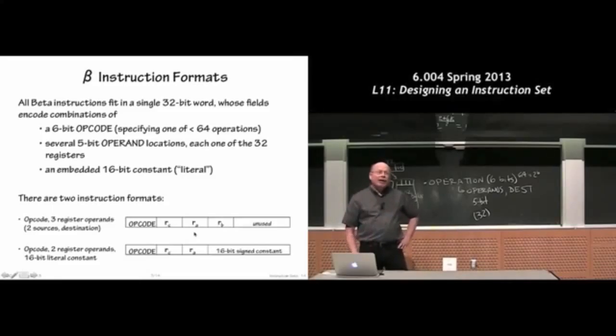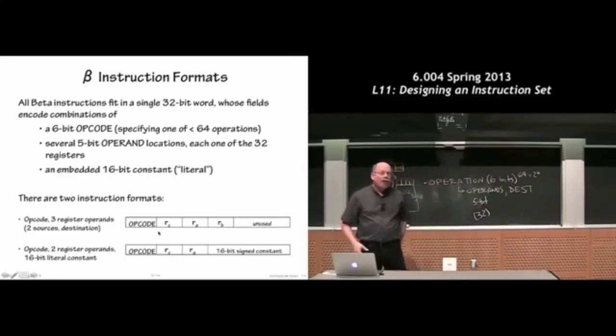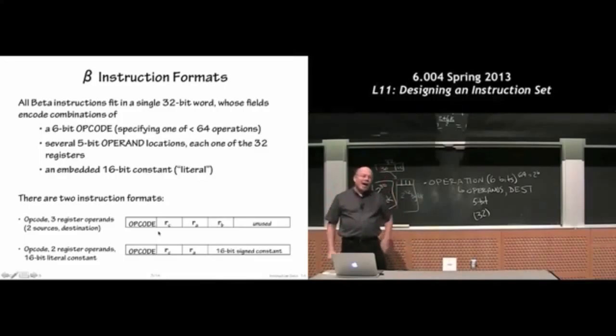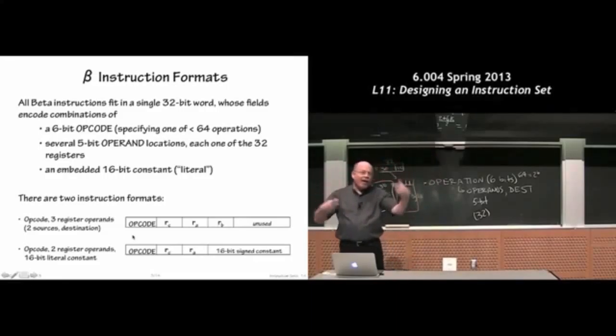It's very simple encoding. And that's why this is a reduced instruction set computer. There's no complication to this at all. When we build the hardware, we're going to use most of the bits of the instruction directly as signals in our electronics to actually control the address of the little register memory, and which value we're going to be reading out, the destination address, and then we'll just have a little ROM that will help us decode the opcode bits into the appropriate control signals for all the different things, ALUFN and all the other things we'll want in our data path.